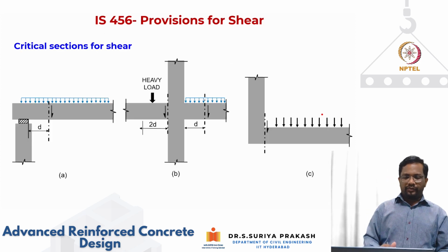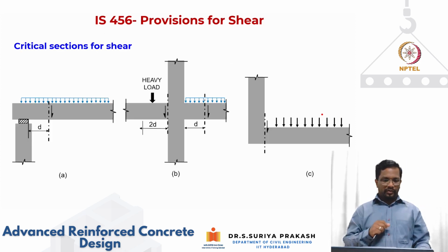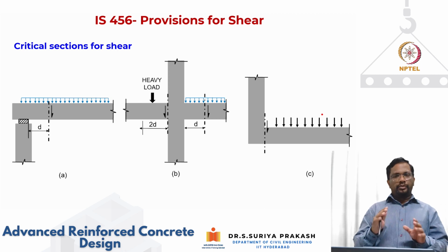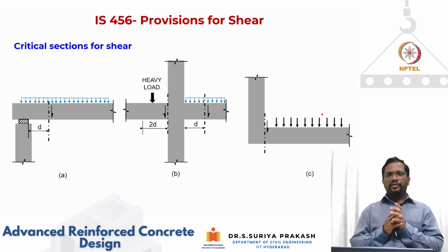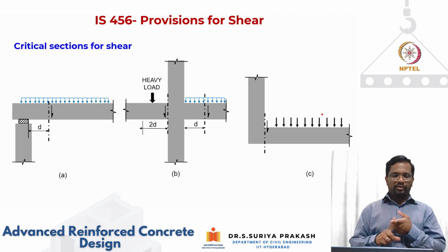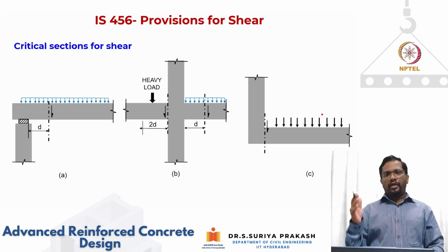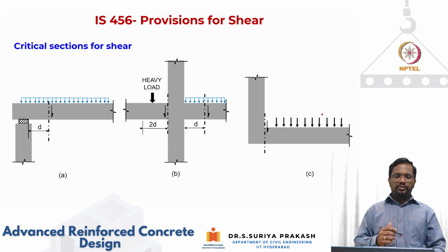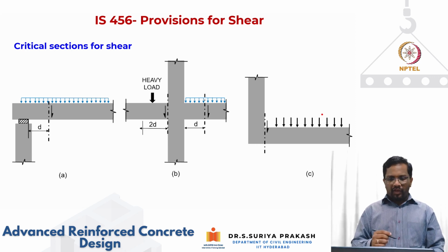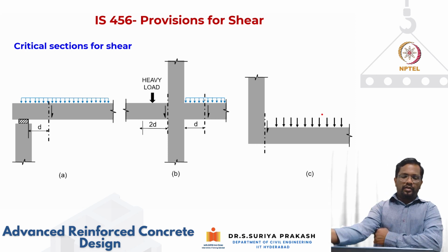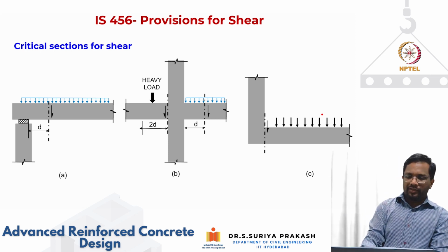Right. So first, let's talk about the critical sections for shear. Right. So before we do that, I think structural analysis is very important. We need to accurately be able to calculate the variations of bending moment and shear force diagrams, right, for an element. Once we do that, now what is the section that we need to take for design? Now, for demand, the code says that there are three scenarios.